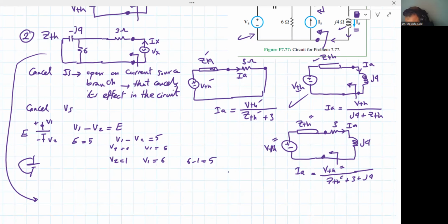So we know that if you have a source and this source has a voltage E, for example, and they produce a current, so the whole resistance is V over I. So in that case, Z Thevenin is equal to Vx divided by Ix. That's I'm telling you how to solve it generally. I know there are other ways, but you're gonna get the same solution, of course.